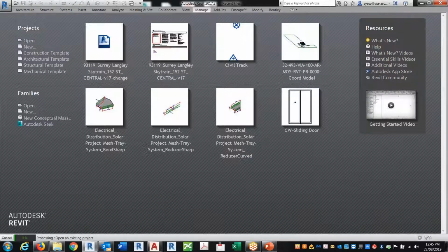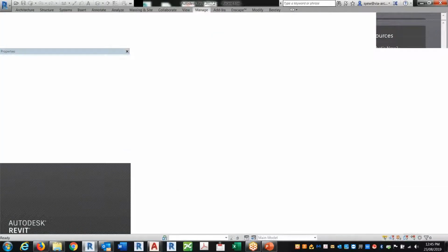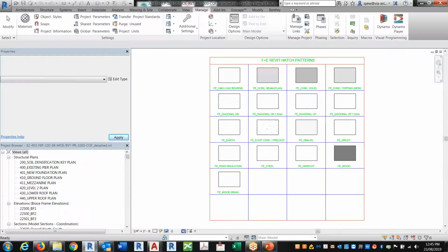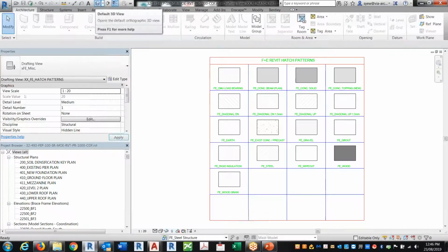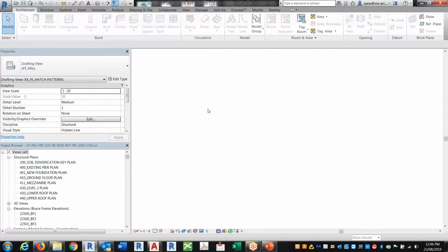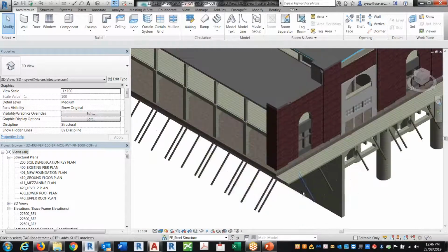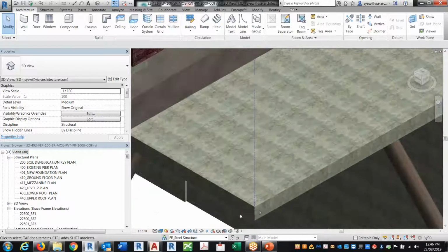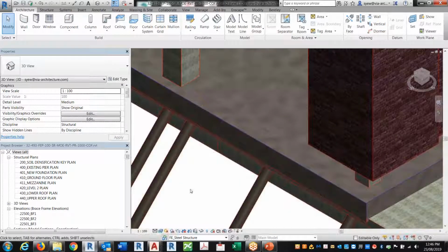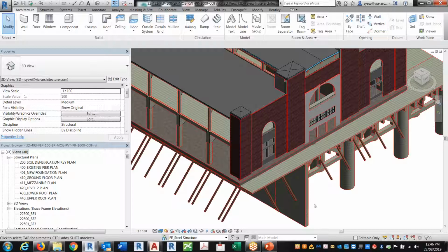The first thing you want to do with this model is change the material to a different color, because right now Enscape doesn't have the ability to override materials with a specific color. So what you have to do is change the model to a different color. Right now you notice that their color looks like this, with concrete and everything, so you want to change it to just one color.